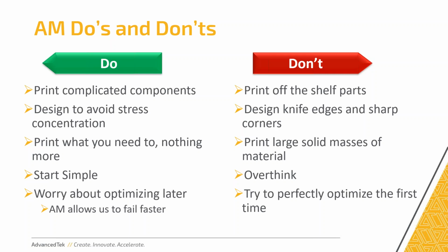We're always going to want to avoid stress concentration because there's some level of heat and stress applied in each 3D printing process. So avoiding kind of those knife edge corners, sharp corners. A lot of times the 3D printing process will round itself out.